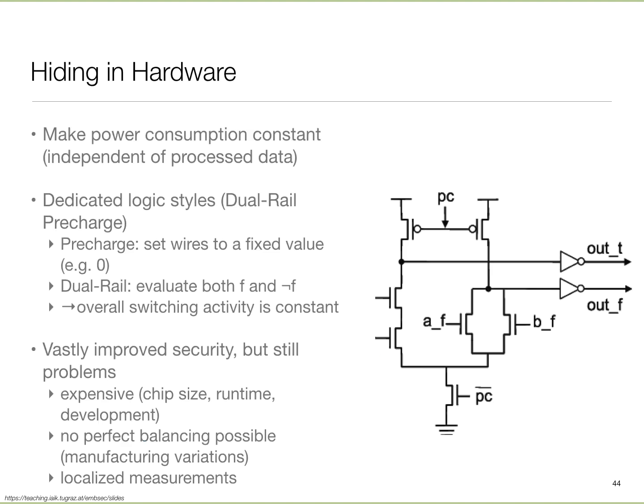Okay, I think I've talked about hiding in hardware. So this is an example of a circuit, for those of you familiar with how CMOS circuits look. This circuit always takes, instead of just X, both X and X bar. And instead of producing just Y, it produces Y and Y bar. So it's what is called dual rail logic. Every variable is carried both in its positive form and a negative form, and I'm always producing the true output and its inverse also.